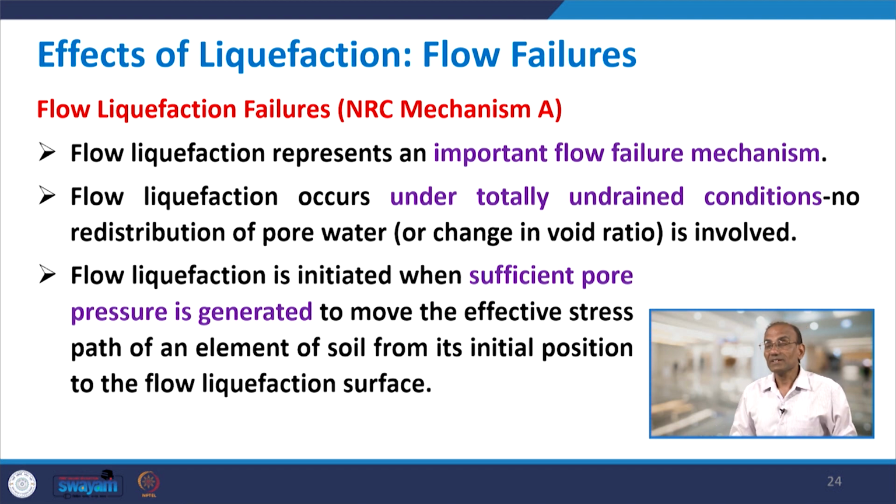So, here we assume that drainage is not allowed, and there is a change in the excess pore pressure continuously, and that change in excess pore pressure is leading to the flow liquefaction. Flow liquefaction is initiated when sufficient pore pressure is generated to move the effective stress path of an element of soil from its initial position to the flow liquefaction surface.